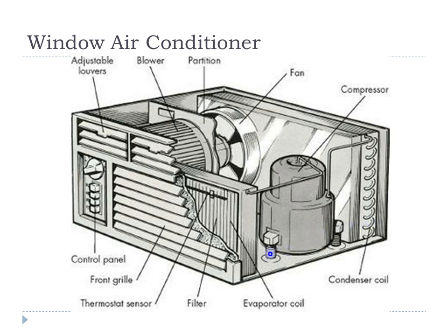After the expansion, since the refrigerant becomes so cold, at such a low temperature, you take it to the evaporator coil. You can see it here, and from this evaporator coil the refrigerant is taken to the compressor. So basically you can notice all of the main components which are there in a window air conditioner.